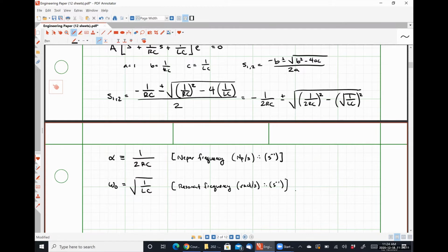If you've ever seen a construction site that uses scaffolding, if you set up your scaffolding and tap it with a wrench, the audible tone you hear is the resonant frequency of that system. That's actually one way they test to make sure the scaffolding isn't going to fail. If you load up the scaffolding and hit it and hear a high frequency, you're great. As you put more weight on it, the resonant frequency decreases. If it sounds like a ping, you're good. If it sounds like a thud, it's about to fail.